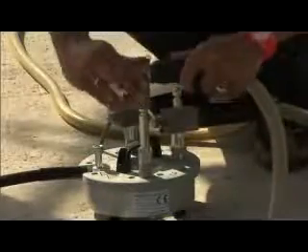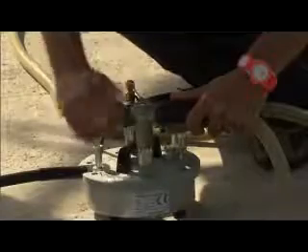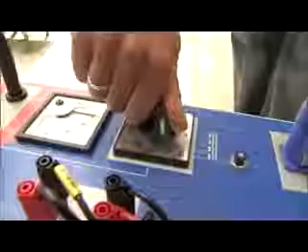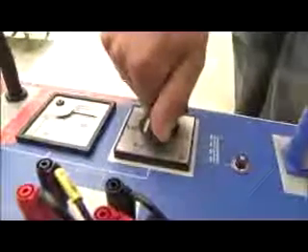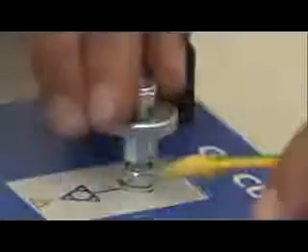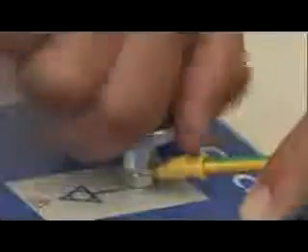The equipment is connected to the overhead line through a grounding box, which also protects the user and the equipment against unexpected events on the line. CPCU1 includes safety isolation transformers, which also condition the signals from the CPC100.